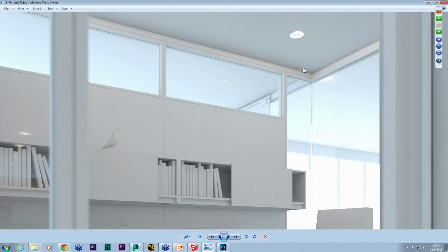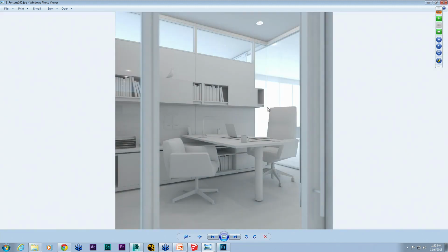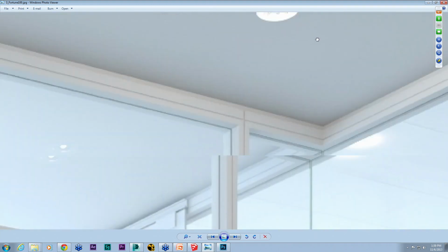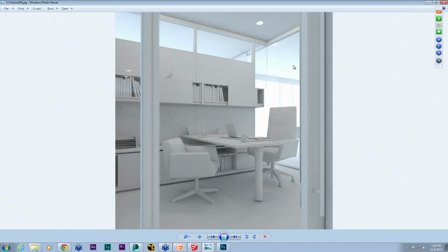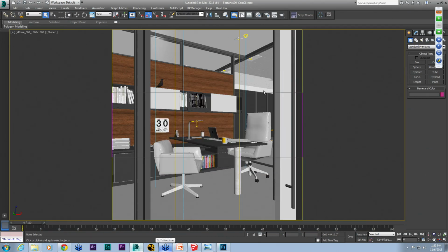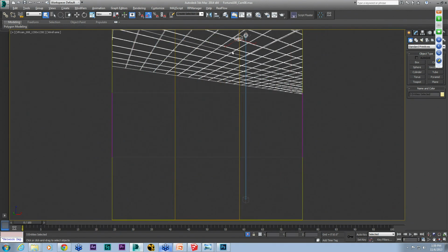And another thing that we like to do is actually turn these ones on in 3D with a V-Ray sphere light that only affects the light itself. So we've got an exclusion going on here. This scene's a little heavy. Might take a second here.